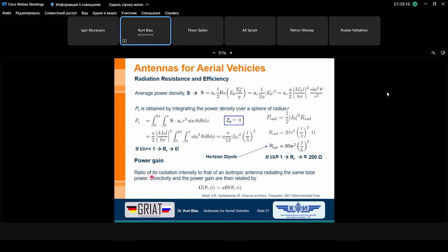And the directivity and the power gain are only related by this very primitive formula: the gain is nothing else than the directivity multiplied by the efficiency. If the efficiency is very high, meaning the inner losses of the antenna are very, very small, because it's full metallic, not zero, then the efficiency E is in the near of 0.95, 0.99, and so on. And then we can say the power gain is nearly the directivity.